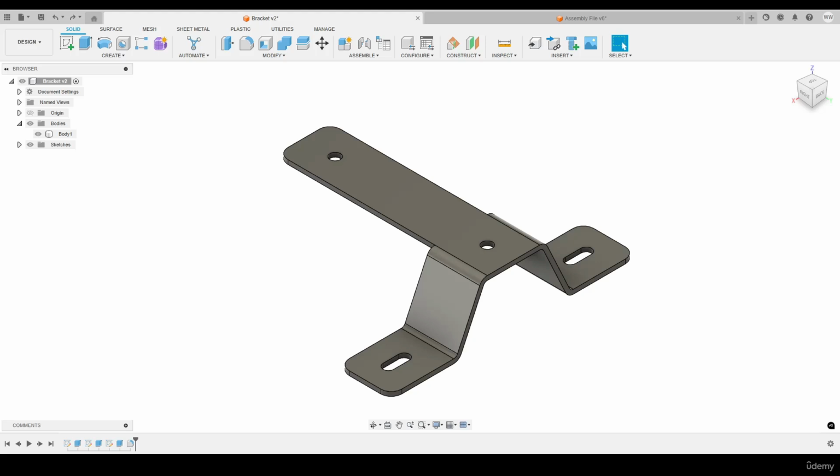And so if we want to understand the weight of a part, for example, we need to apply a material from Fusion's library of materials to get a realistic representation of the weight based on the material's associated density properties and the volume of the part itself. And Fusion will pre-calculate this for us.